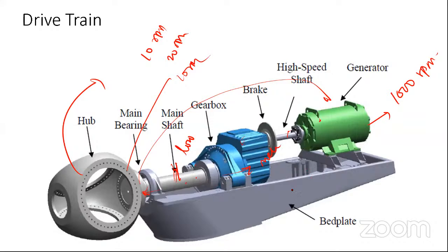So in between, like a two-wheeler and a four-wheeler, we give step up and step down of the speed, but here it is only a step up of the speed, because here I have 10 rpm and I need 1000 rpm. Now the gearbox is there, so the gearbox will step up the speed from 10 to 1000 rpm. How? The gear ratio 10 by 1000 equals 1 by 100. So 1 is to 100 times.